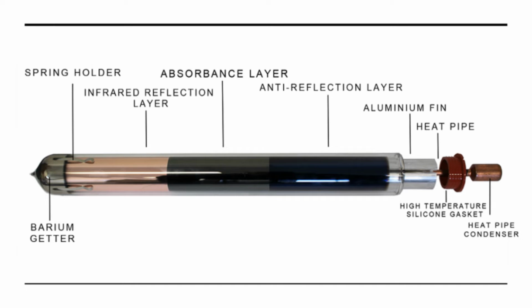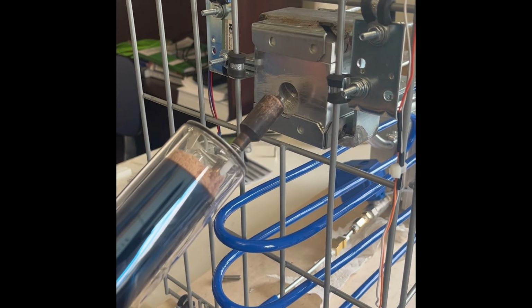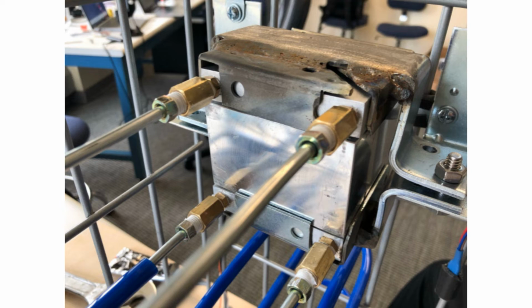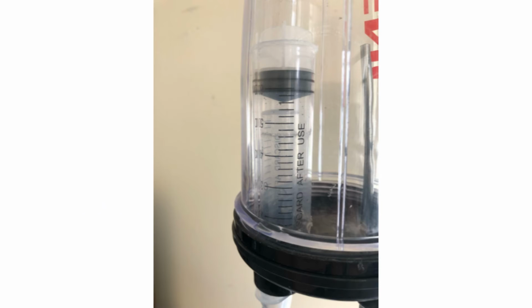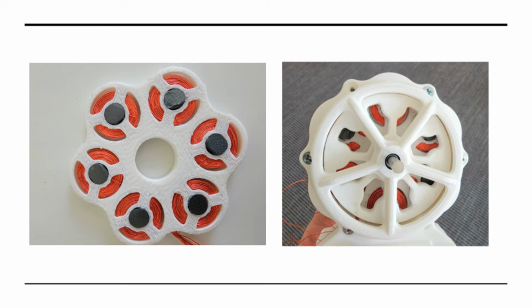Using conductive and convective heat transfer methods, the heat energy is transferred from the copper tip to an aluminum block, in which a hole is drilled for insertion. The fluid then extracts energy as the piping passes over the block's surface, both above and below. After heating, the fluid moves into a flow-controlling bell siphon system and down over the paddles of a water wheel, which rotate gears that are connected to a generator.